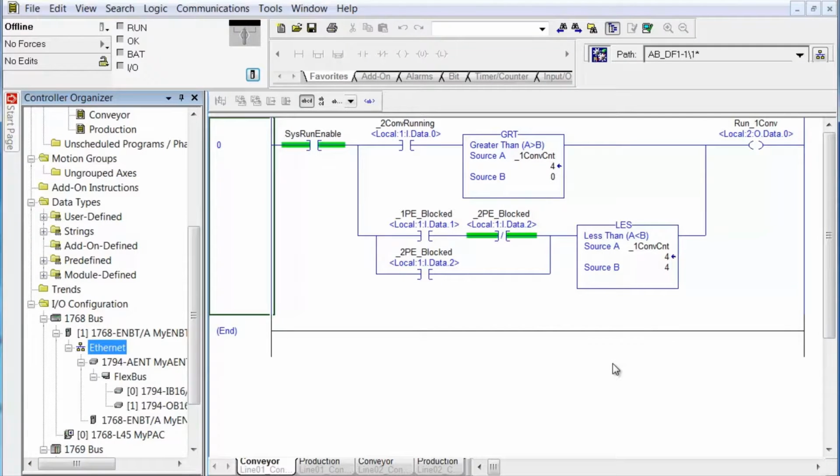So save your project. Remember that it was built with RSLogix with compact I/O 1769, and we will have gone through this procedure of adding I/O several different ways under several different conditions with RSLogix, which is probably next on the list to do something with RSLogix. We've done it with L35E and now L45. So you see the procedure is basically the same.